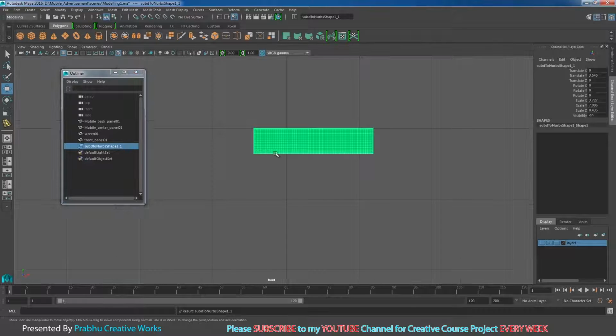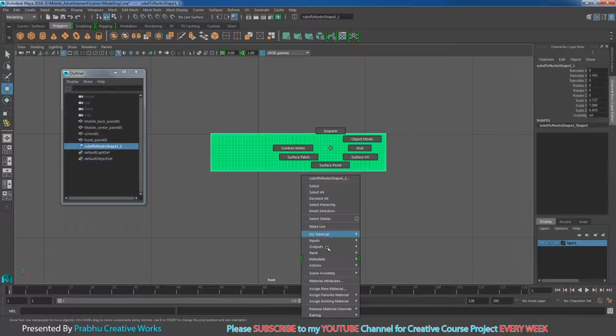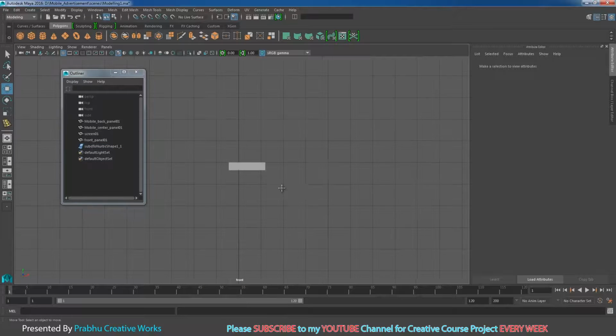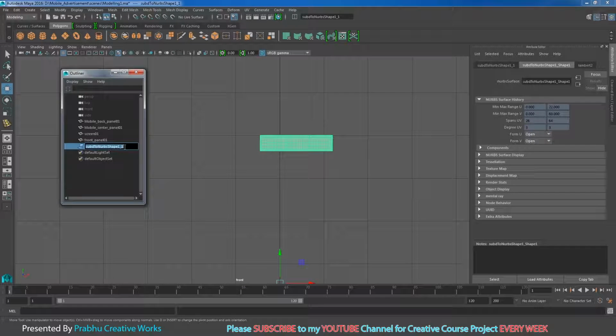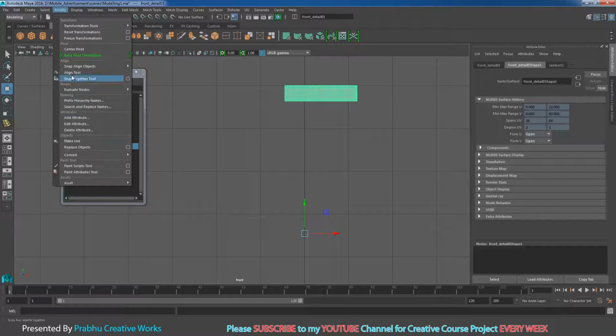So when you convert the sub D object to NURBS, the color will change. So don't bother about this. You want to apply Lambert to clear this one. So right click and choose assign new material and apply new Lambert. So that's it. Now I want to rename this object front underscore detail 01. So detail 01. So now it's a NURBS object. So I want to change my pivot. So select your NURBS object, go to modify and choose center pivot.